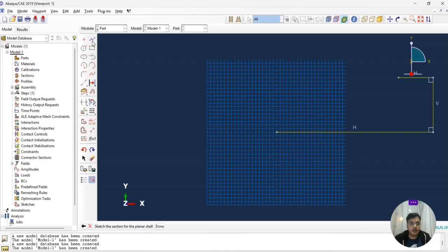Now we define this particular length, going to be 0 comma 50, which is 1.5 times less than this one. Then we define the length here, and it's going to be 150 comma 50. Now we will define the edge, so we can use the center arc. We have to keep the center, and then do endpoints. Let's say the radius will be 35.